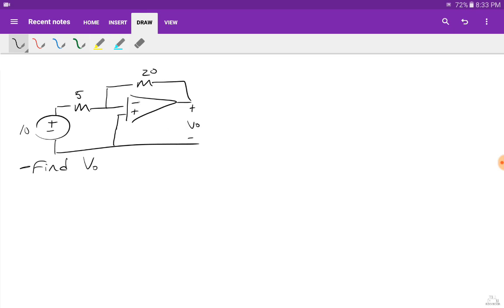Note the N terminal of the op amp is on the top side and the P terminal of the op amp is on the bottom side. Okay. So remember, you want to basically do KCL at the nodes with the stuff. If you look at which nodes have the stuff, you have N, P, and the output. Output is connected to the N. N has some stuff. P is connected straight to the ground. This whole bottom terminal we can see as a ground. So if P is connected to the ground, it has no stuff. N has the stuff, so all I have to do is do a node equation at N.